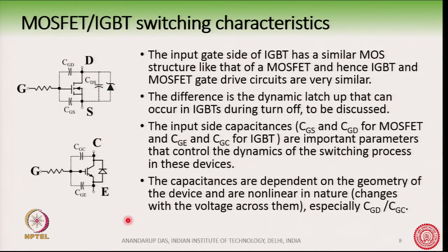The gate drive circuits, or the analysis for the gate drive circuits, are more or less the same for both IGBT and MOSFET. There are some differences, of course, like there is a dynamic latch up that can occur in IGBTs during turn off, but relatively speaking they are very similar. The gate drive circuits for IGBTs and MOSFETs are very similar and they can often be interchanged. Now, the input side capacitances.